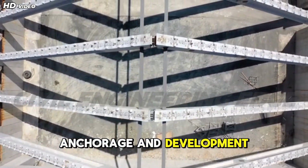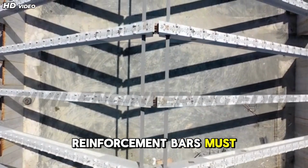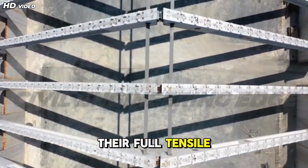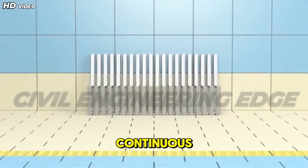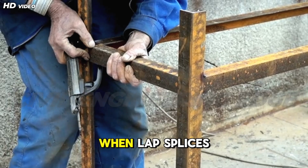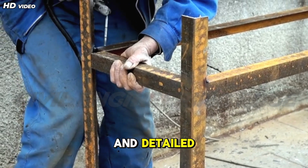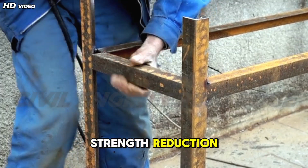Anchorage and development length are equally important. Reinforcement bars must be embedded sufficiently into the concrete to develop their full tensile strength. In columns, longitudinal bars should be continuous wherever possible, with splices located away from regions of maximum stress. When lap splices are necessary, they should be staggered and detailed as per codal provisions to avoid sudden strength reduction.